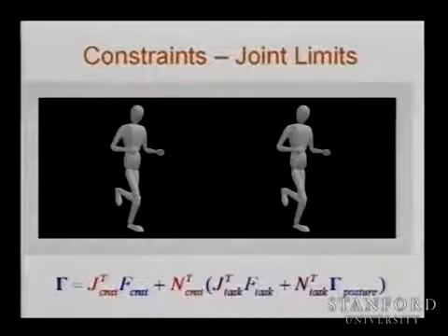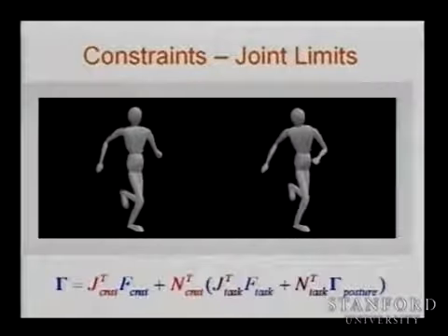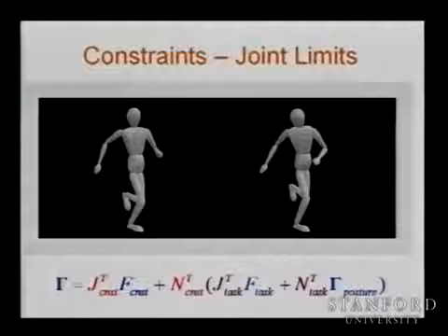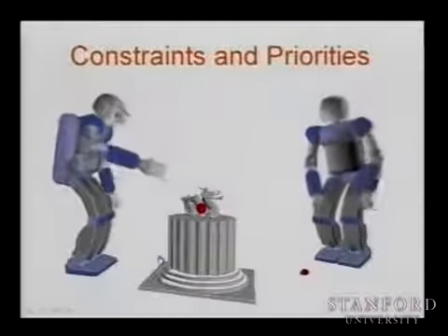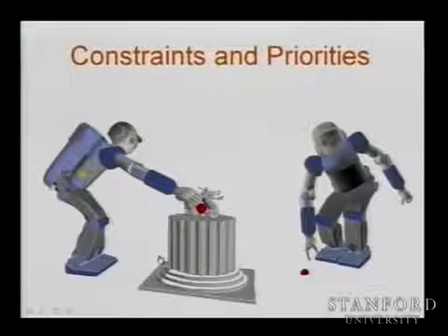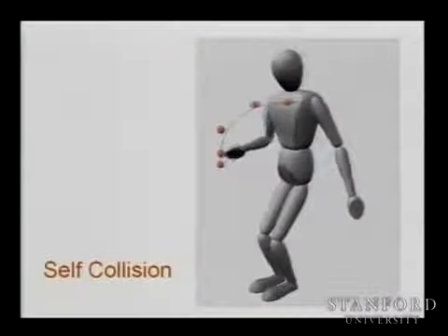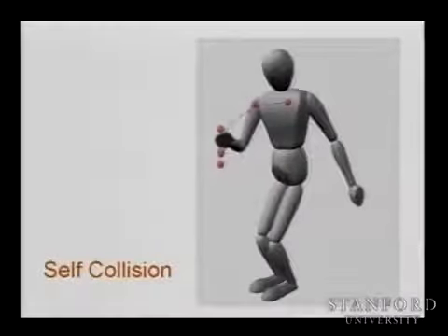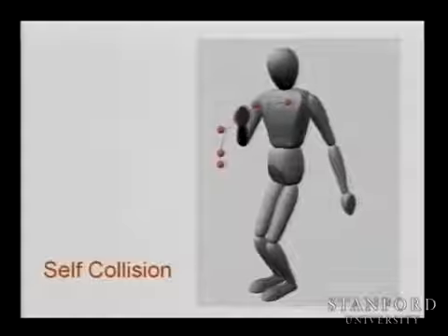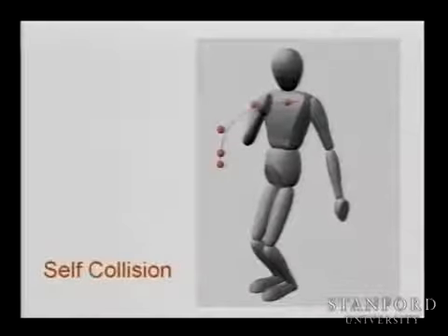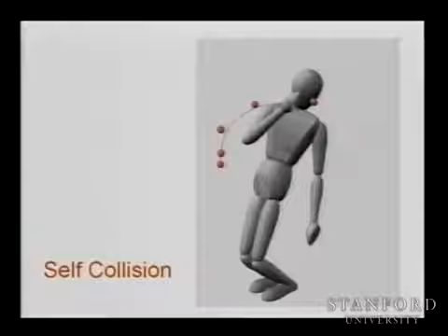And now the robot is moving, and you can see two different postures because you have hip limits. Here you are stuck, you cannot reach because of joint limits. Here the body is going to move away to avoid self-collision. So the trajectory is going through the body, and the body will move away automatically by these repulsive forces.